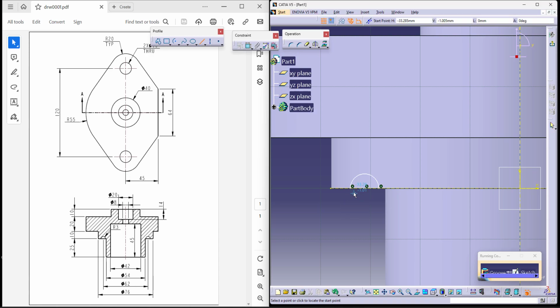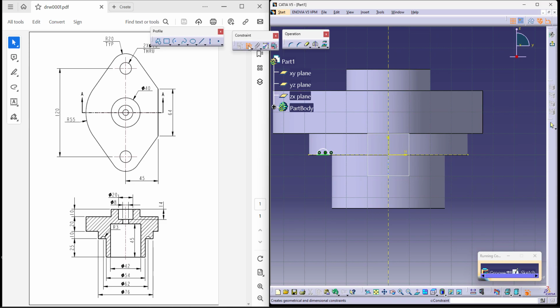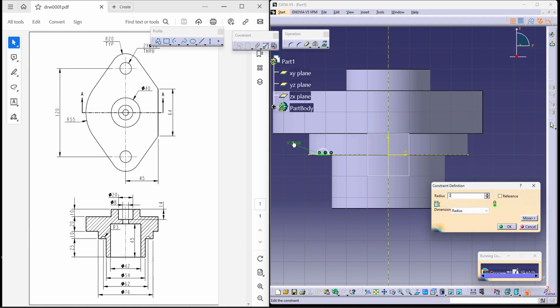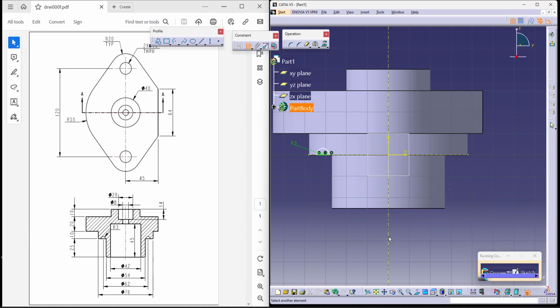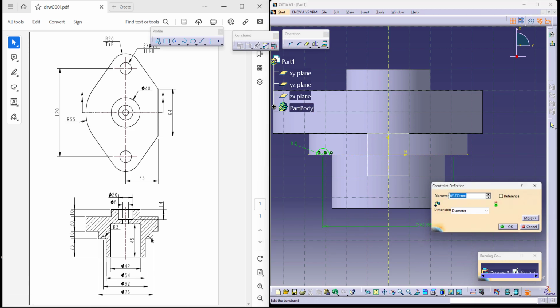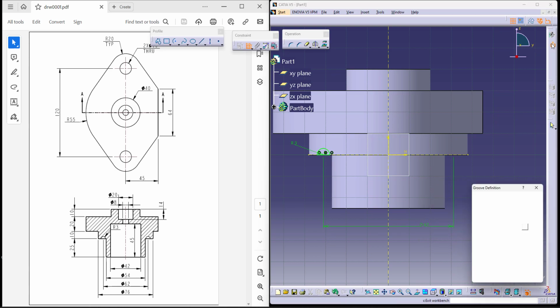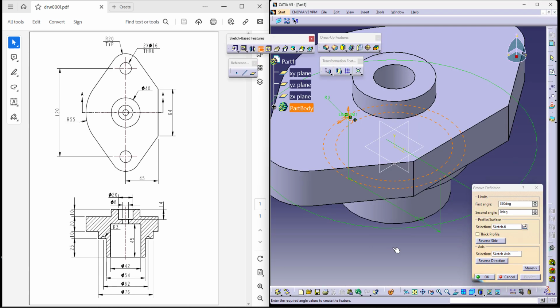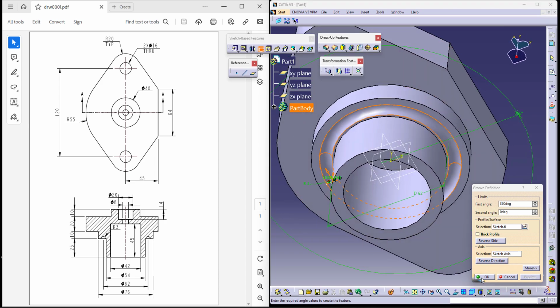The center is actually matching, the center to center dimensions are already given. So let's take that as well as give the arc dimension. Arc is actually 3. We know that the center to the end axis dimension is provided, and center to center is supposed to be 62. We just got really close. Now, when you remove it, it removes this one, as you can see.